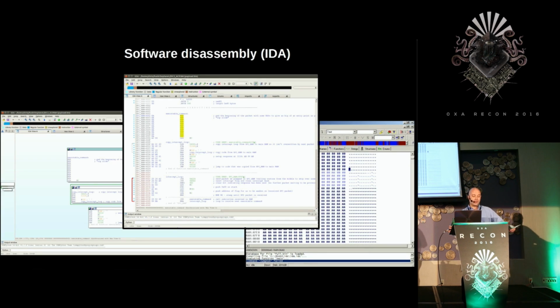So now with the ROM contents extracted, the software can be disassembled and analyzed. The first step was to identify the CPU architecture. Studying the binary dump, it appeared to be an 8-bit CPU, but was not 8051 or 6805 or the other processor types I tried first. Eventually, I tried disassembling a 6502 and the code made sense.